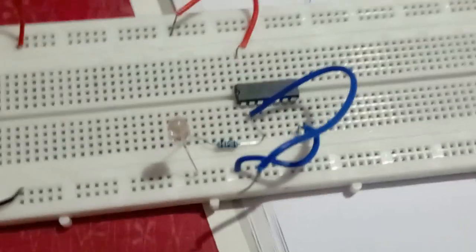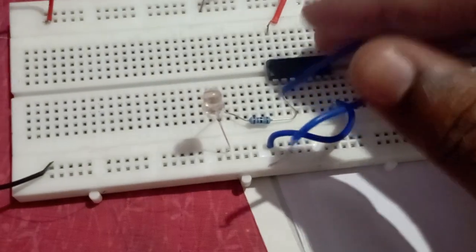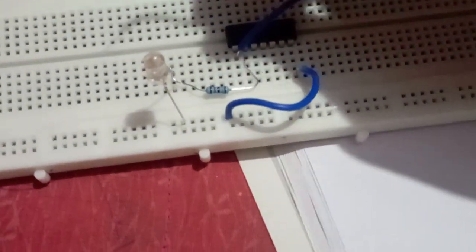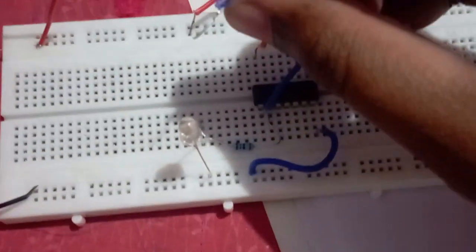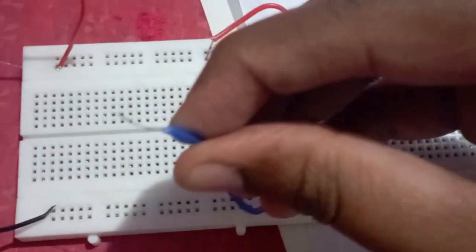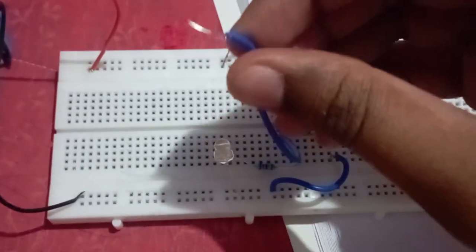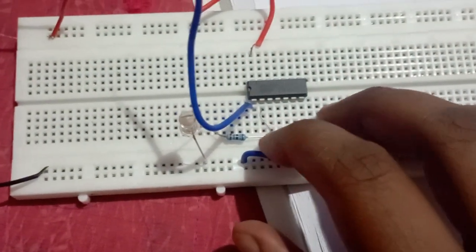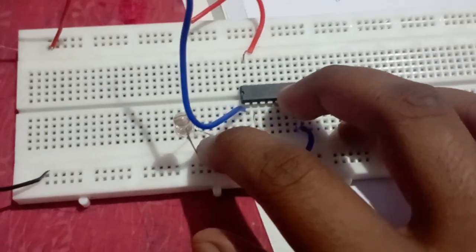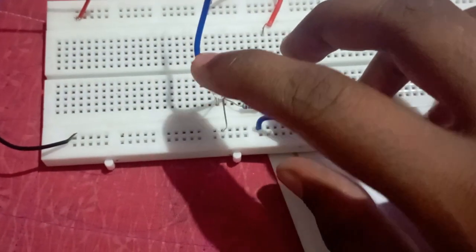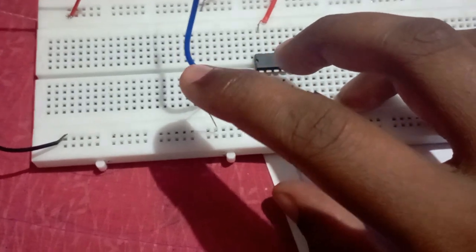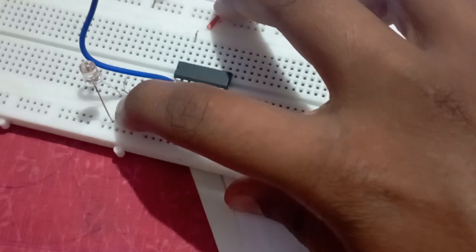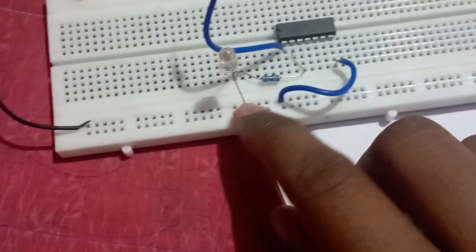So this is the connection, how it is going to be. How I connected is that this is an IC. I have connected pin 1 for an input, and I have given an open wire to give an input, which is going to be a 0 or 1, that is, I am going to give 0 volts or 5 volts. And for output I have connected one resistor, and I have connected in series an LED, so that the LED must not burst. The positive side of the LED I have connected in series with the resistor, and the negative I have grounded here.